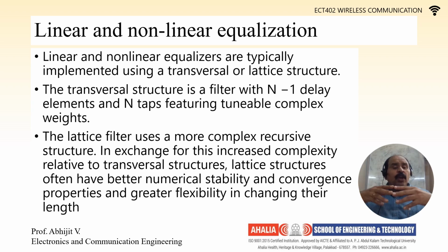A lattice structure uses the more complex RLS algorithms. For this increased complexity, what we have is numerical stability and convergence properties and greater flexibility in changing their length. So if you could write down these points in your exam when there is a question about what is the cost that you have to pay for a lattice structure which is more complex, or what is the advantage of lattice structure over transversal structures in equalization, you can answer with only these points.